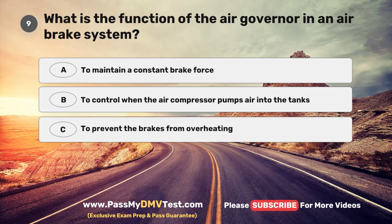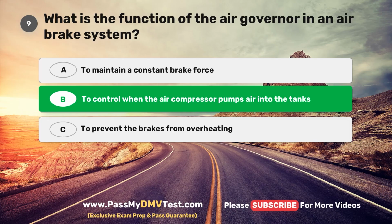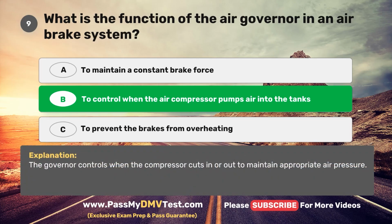Question 9. What is the function of the air governor in an air brake system? A. To maintain a constant brake force. B. To control when the air compressor pumps air into the tanks. C. To prevent the brakes from overheating. The correct answer is B. To control when the air compressor pumps air into the tanks. The governor controls when the compressor cuts in or out to maintain appropriate air pressure.